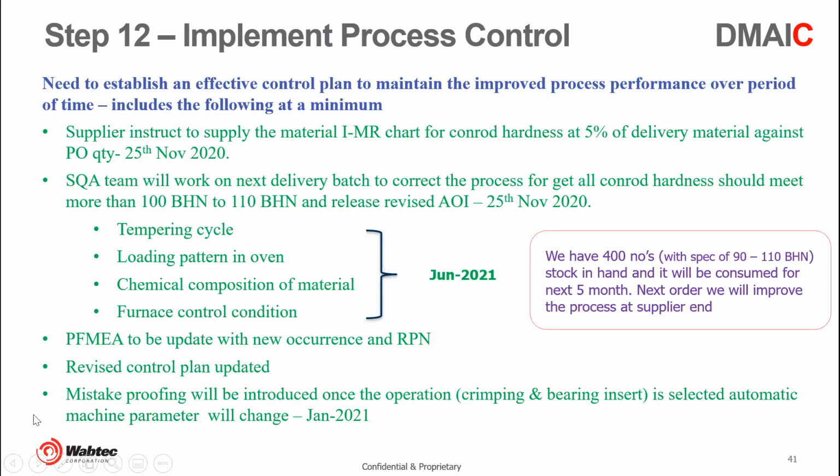Okay, sir. We went to the supplier and saw how many parts were lying with them, and we could take a call on how do we lay the specifications at the supplier end for hardness. So that's it. And of course you have to revise the various documentation of PFMEA and control plans for mistake proofing, etc. So that concludes the presentation.